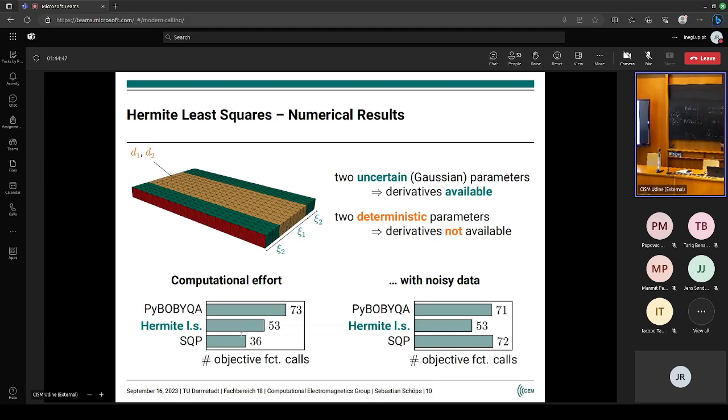Similarly, if you do a finite element approach, and you have the idea during the optimization to increase the finite element mesh, then you may also end up in situations where your function is more noisy, because you have this model noise, these model uncertainties that come on top. And in these cases, and I think that's also very intuitively clear, SQP performs really badly. It takes way more evaluations, and it may even go in a completely wrong direction, because it may see a difference that is just because the number of Monte Carlo samples has changed. It's very sensitive to these kinds of noises.